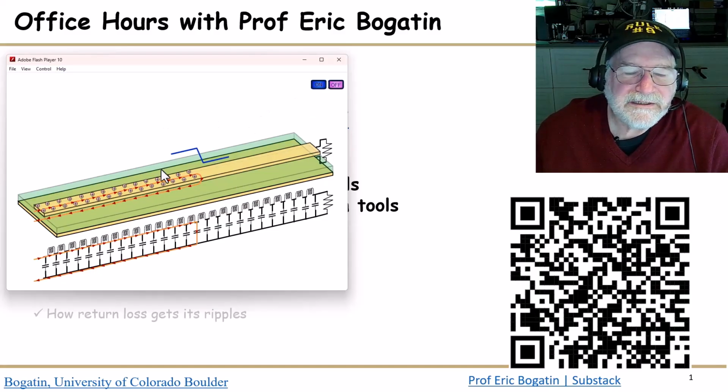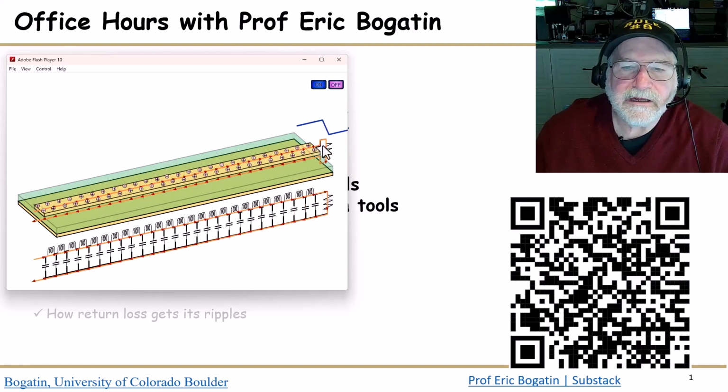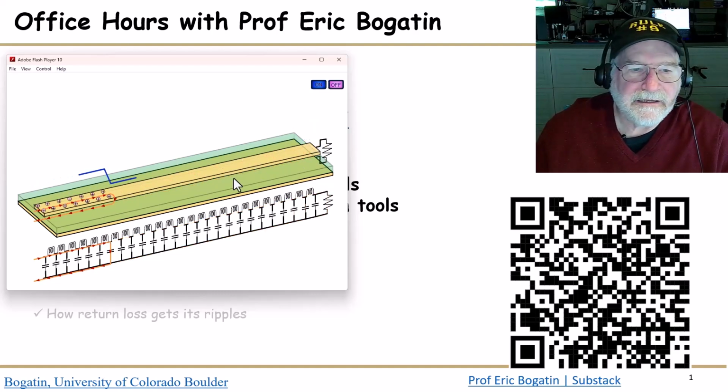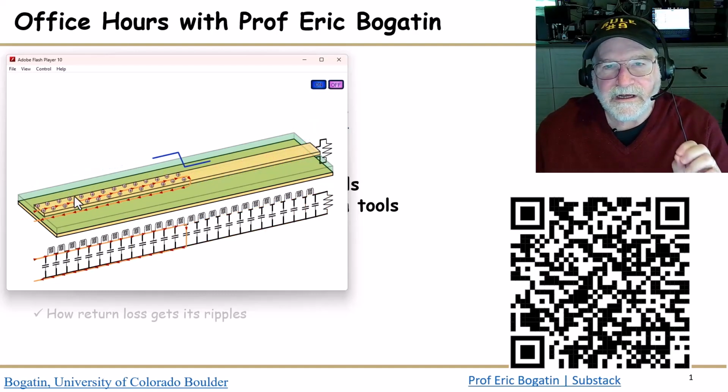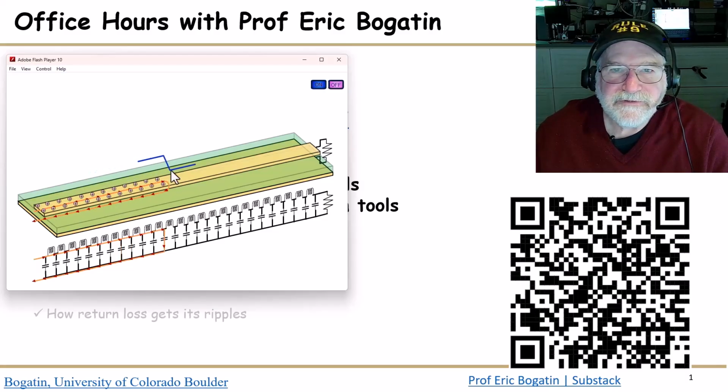We're going to watch that signal return propagate down the line. And so here's that signal return, signal return. In addition to the voltage wavefront, there's also a current wavefront propagating down the line until it hits the end. So we want to adjust our engineering judgment to be thinking about this signal propagating, signal return, where that changing voltage is.